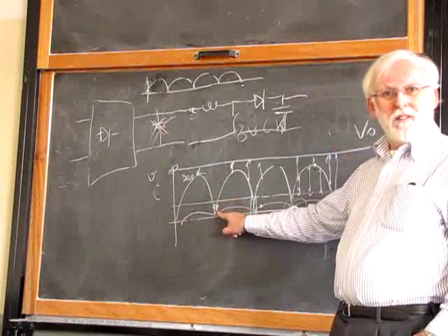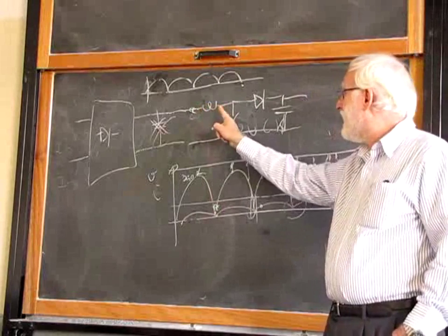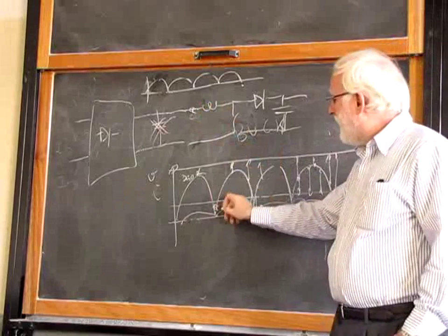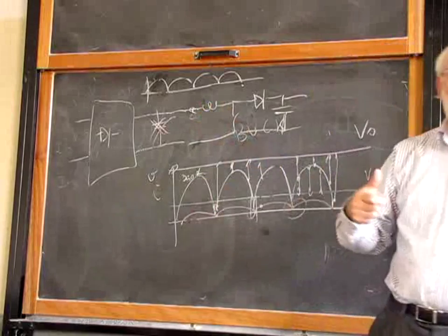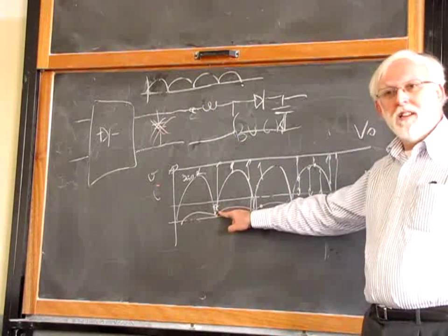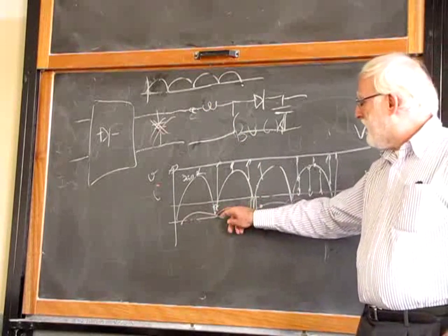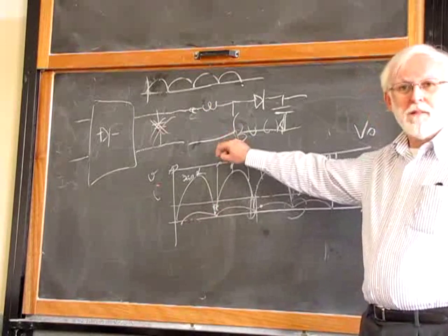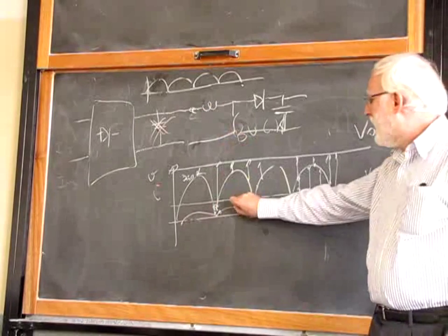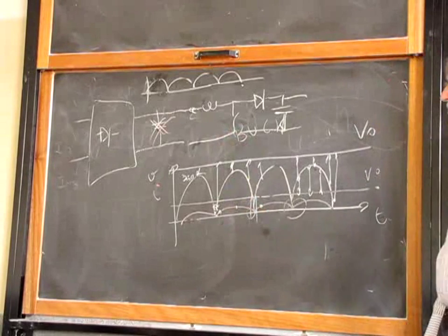So if the current is very low, it means that the voltage drop across the resistances and switches is not so important. So even if here it has to work with a very high boost factor, M factor, the fact that the current over here is very small, 1/10, 1/13 of what is over here, makes me happy, because it means that it can, in any case, boost up taking a small current, because I need just a small current at this point. I don't need the full current that I have to convert in the middle of the cycle. Okay?